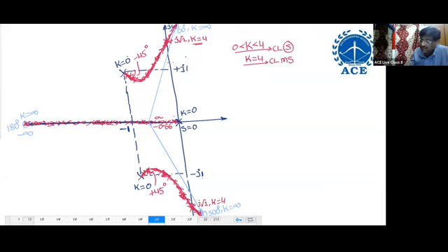Next, one more thing here. What are the different natures the system is having? Overdamped is not there because no 2 poles are on the negative real axis, no breakpoint, no 2 poles meet on the negative real axis. That means no critically damped. But what is this nature? Underdamped. This is a complex conjugate. Complex conjugate means it is underdamped. Here underdamped. This is underdamped.